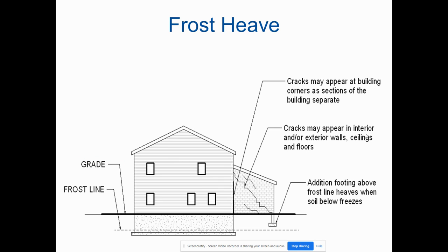So here you see, when the foundation is below the frost line, there's really no problems. But now we have an addition that was placed, and you can see that the foundation of the addition is above the frost line, which is going to be susceptible to heaving. And that's going to result in cracks.